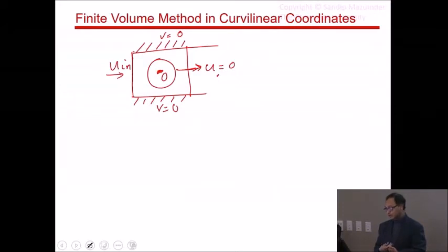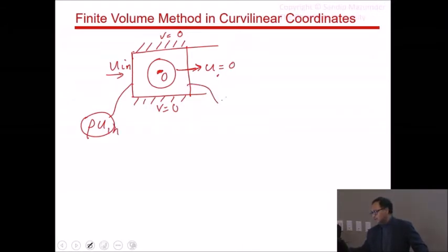So to help that, my suggestion would be you start with inlet velocity everywhere. What that means is you basically have zero mass imbalance. Now, of course, I'm making this argument, but once you solve your momentum equation, things should become better. But with the momentum equation, the same thing happens. Think about this. Your rho u is your momentum link, advective link, the mass flux, basically. So here you have rho u in, here you have 0. So if you think about momentum balance, there's a huge momentum coming in here. There's no momentum going out there.